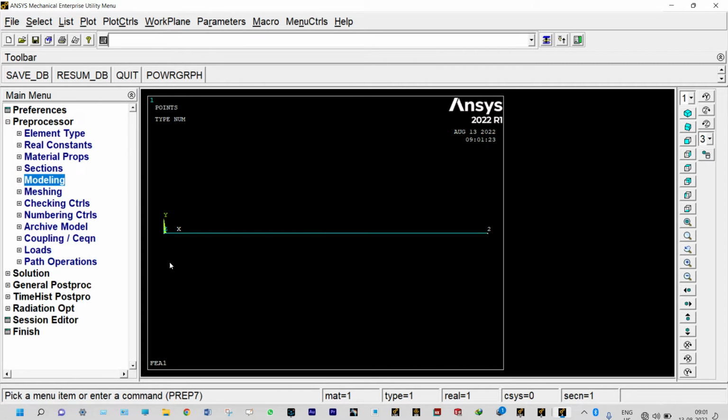Right, now the thing is, we need to mesh it to make more numbers of elements. More the nodes, more will be the elements. So our plan will be to make this line into 10 numbers of divisions. So 10 elements will be there, and it will be having total 11 numbers of nodes, because in between each element 2 nodes will be there, right?